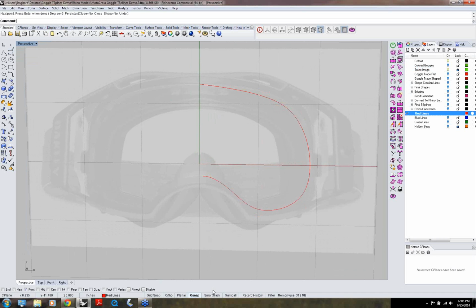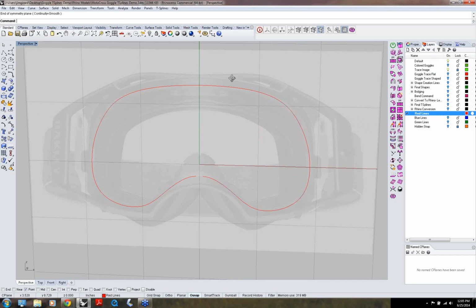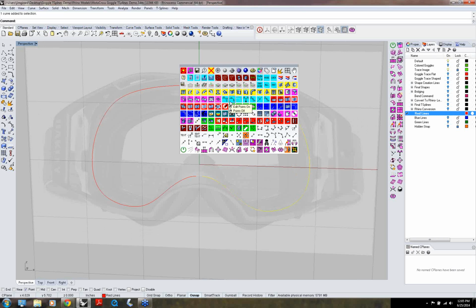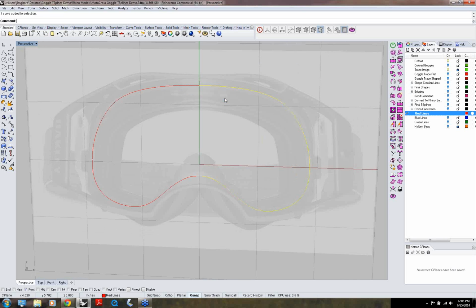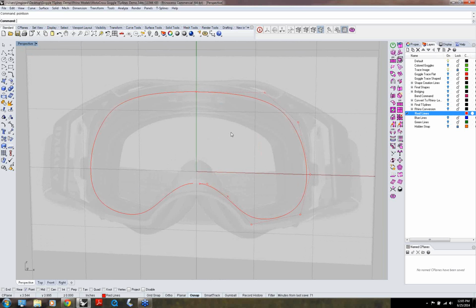And then many of you Rhino users know about record history, and then type in the command symmetry, and it asks to select the curve and then the center. And now as you begin to edit the points on this curve to get it exactly where you want it, it will update and maintain that symmetry. Now this is where I like to use T-Splines.